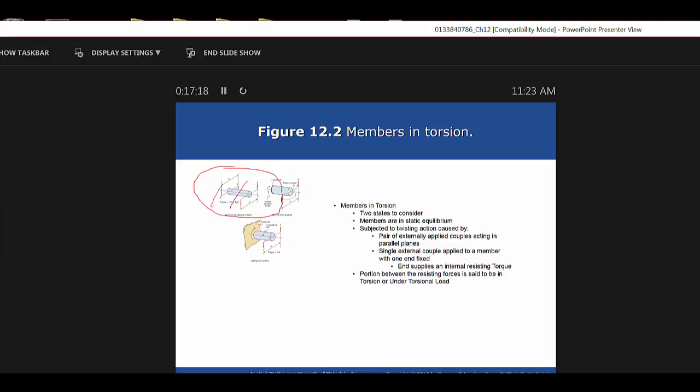Showing that inclined distance. Do what? They are showing in the figure the inclined distance is not straight. The D is making an angle. Well, that's just because it's an isometric view. That would be no different than if we looked at the end of this shaft right here. There's your circular shaft, and there's one force going down this way and one force going up this way. And then the diameter is right here. So that's D, and this is the force, and that's the force. So it's the force times the distance. Does that help? Yes, a lot.